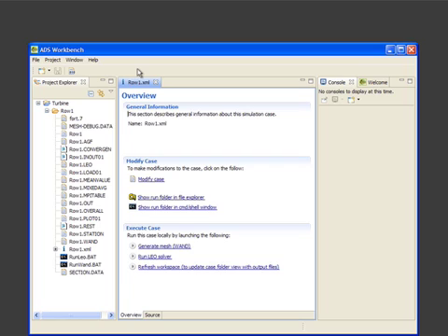For example, design is very iterative. So if you wanted to use the same settings from a single simulation and change, say, one parameter, for example, the exit back pressure, in the case you were doing a speed line, you would have the ability to, in fact, create a copy of an existing case and modify only the data information that you want to modify. We call this the Create from Existing feature. So let's do that now. Let me show you how it's done.